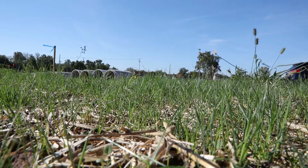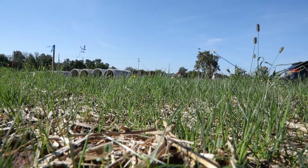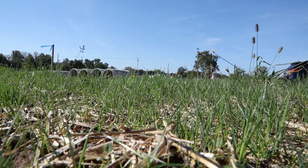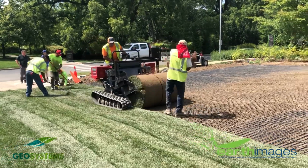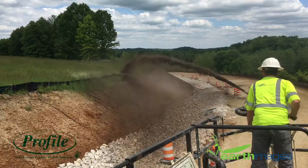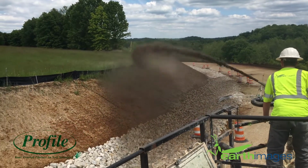Dormant seeding is a temporary or permanent seeding application at a time when soil temperatures are too low for germination to occur, usually less than 50 degrees Fahrenheit. And frost seeding refers to applying seed in late winter when soils are in the freeze-thaw stage. Sod placement means to lay a continuous cover of grass sod over exposed soil. Hydro seeding is applying a slurry of water, wood fiber mulch, seed, and fertilizer to prevent soil erosion and provide an environment conducive to plant growth.